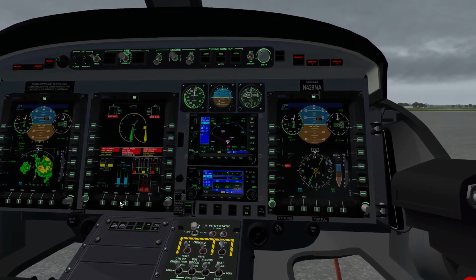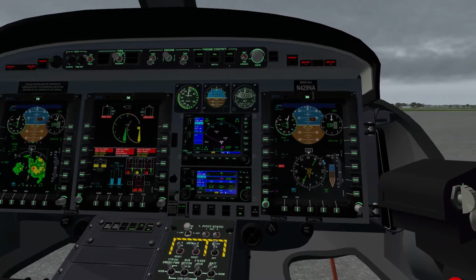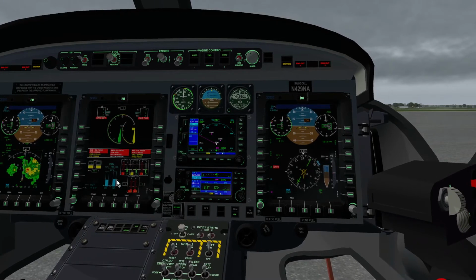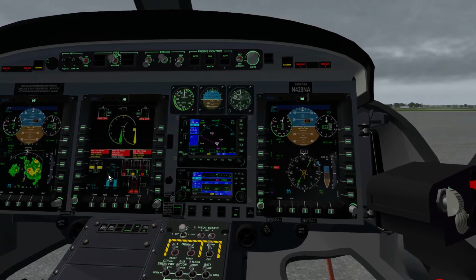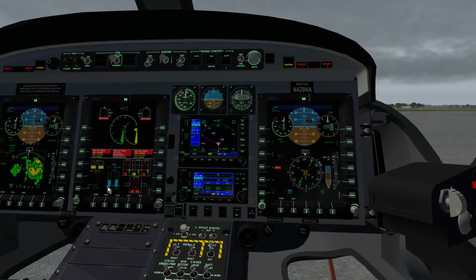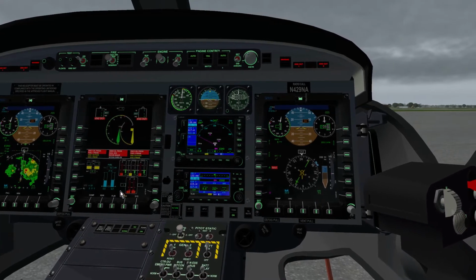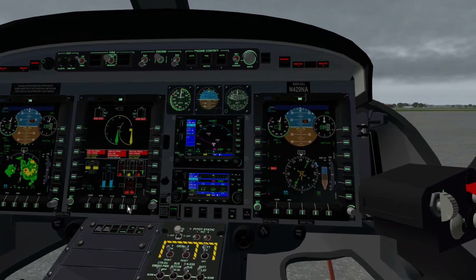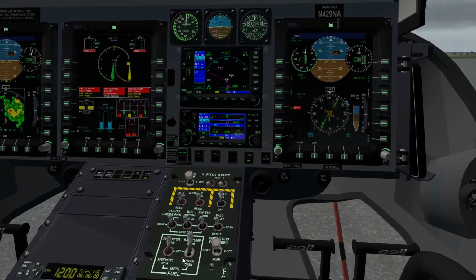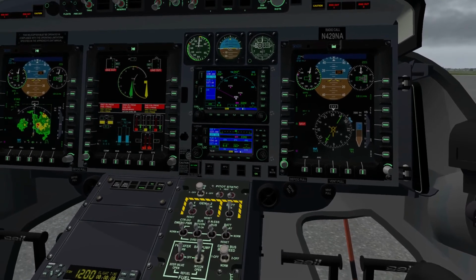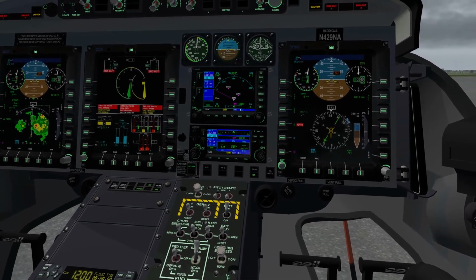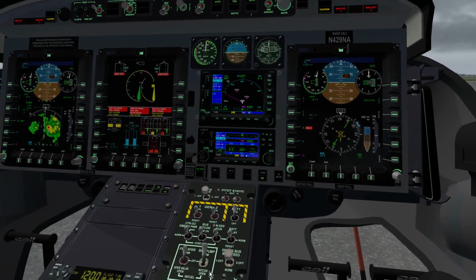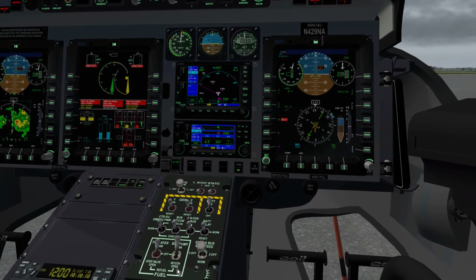On the Bell 429 we've only got 4 fuel tanks, so there's a bit of a muck around, and you will find that the fuel comes down in stages, left, right, left, right, apart from the last sort of 100 pounds when they both come down together and the warning lights will come on together. But make sure for this to happen that you have the forward transfer and the balance pump at normal. By default when you switch on they will be at normal,